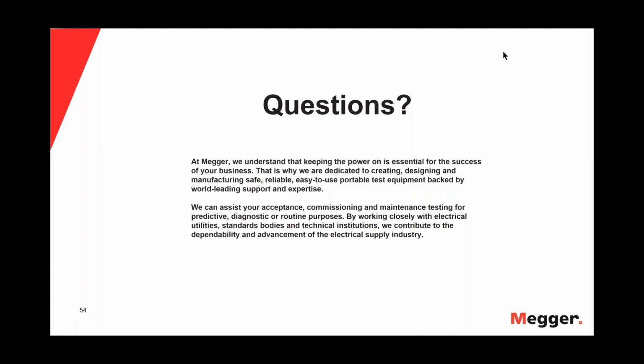So, like I say, sometimes you're lucky that there is enough change in the insulation, causing that leakage, that it will change the impedance when you measure it, and that way you can see.